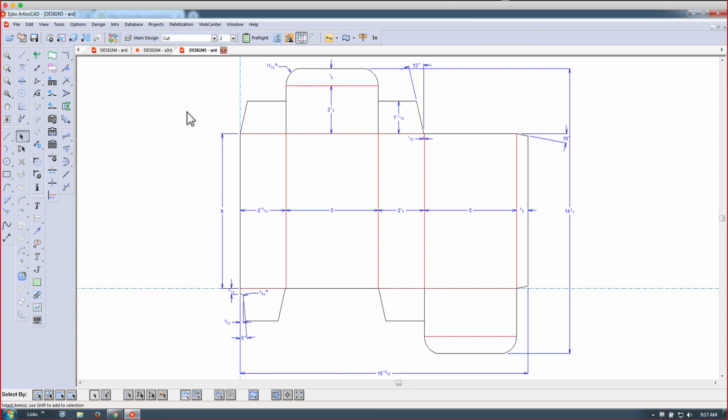Once we pass this along, the graphic designer typically also needs some additional information, such as varnish free areas, and very important as well is bleed. So bleed lines, I would always recommend to create these around the entire outline of the design, depending on whether these flaps are printable or not. Typically, we want to include this. This becomes important when we start stepping and repeating these out on a manufacturing layer.